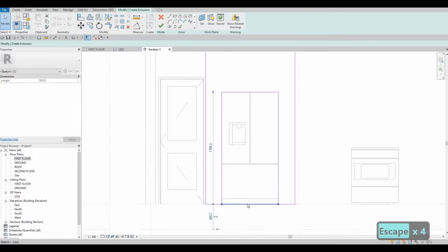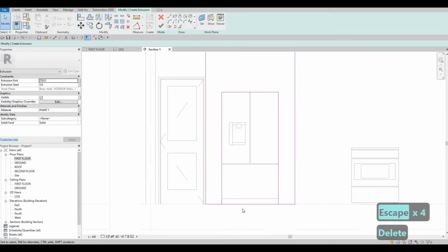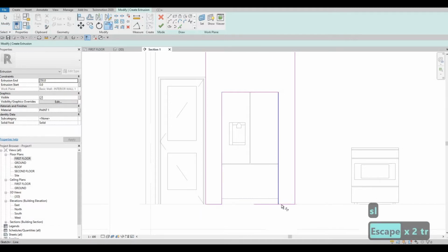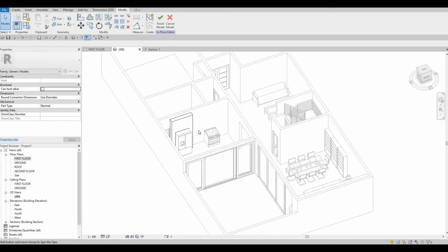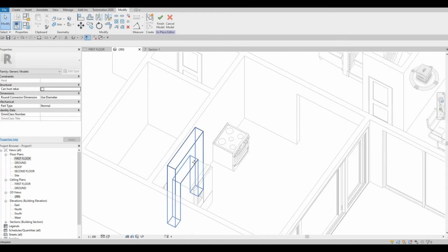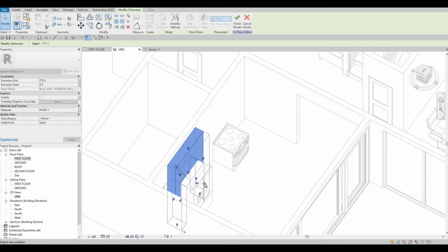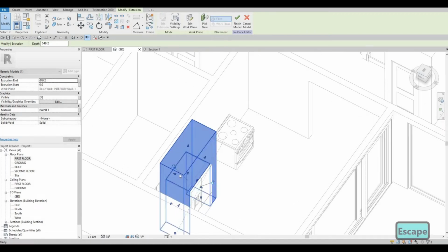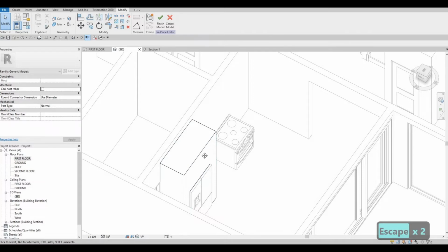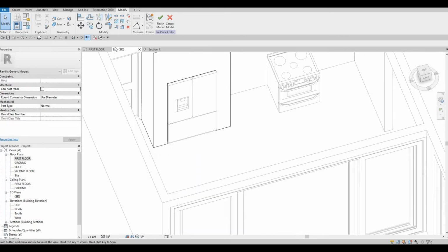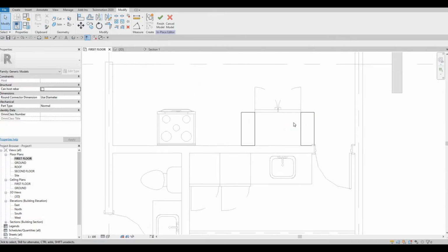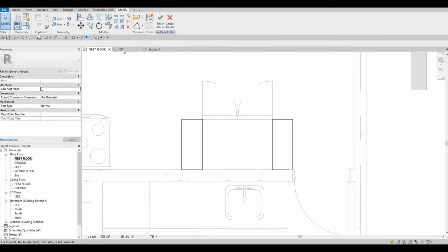And then here I'm going to delete this. This will be SL, split element, and then TR, trim and extend. Click finish, go to 3D. So we're gonna keep on flipping from 3D to section and even some of first floor. So this 3 we need, and then if we check it, we were able to do it properly.